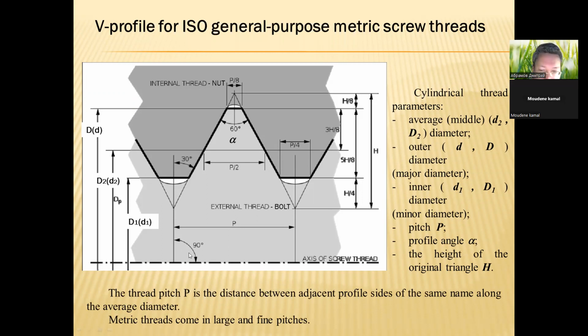Okay, the thread pitch, P. Okay, teacher. Excuse me, previous slide. The thread pitch, P, this distance, these dimensions. The thread pitch, P, is the distance between adjacent profile sides of the same name along the average diameter, or middle diameter. Metric threads come in large and fine pitches.